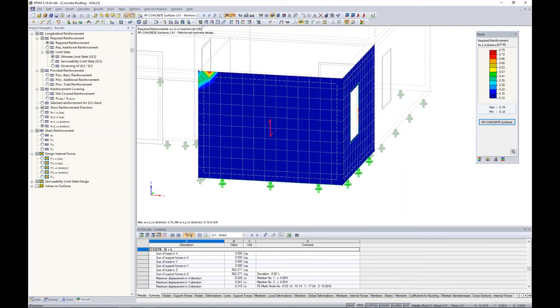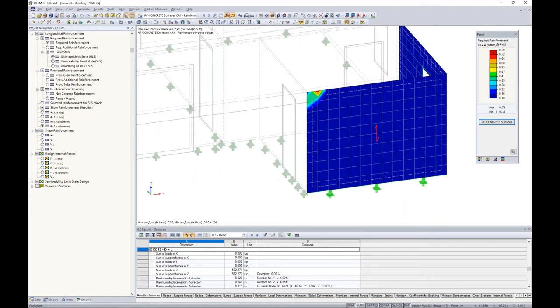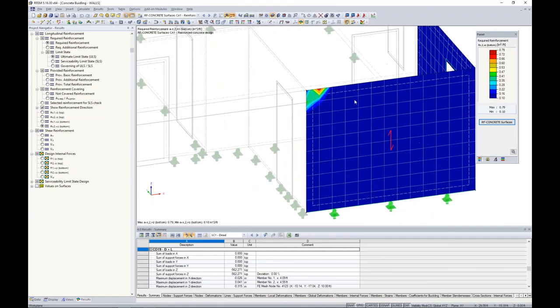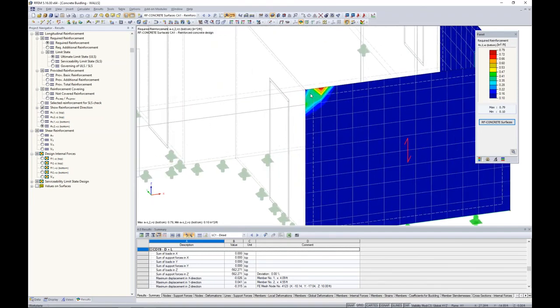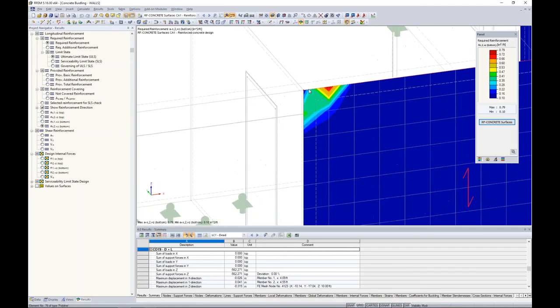required. So this tells me that we have an issue called a singularity. Now, if we look at this corner here of this wall panel, we have this additional wall panel framing in from 90 degrees. Remember, we have our rib member framing in all to this teeny tiny FE mesh point in the corner. Well, in reality, this is not just an issue within RFEM, but with all finite element analysis software, that the load isn't going to be distributed at this one single little mesh point, but rather we're going to have better load distribution in real life.